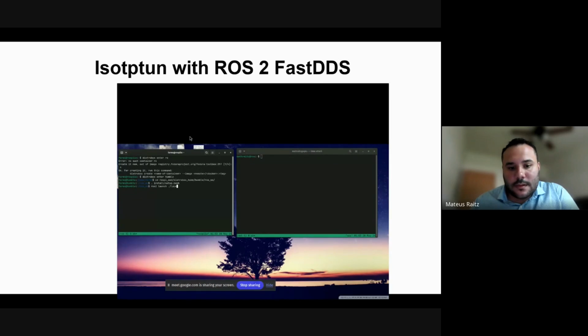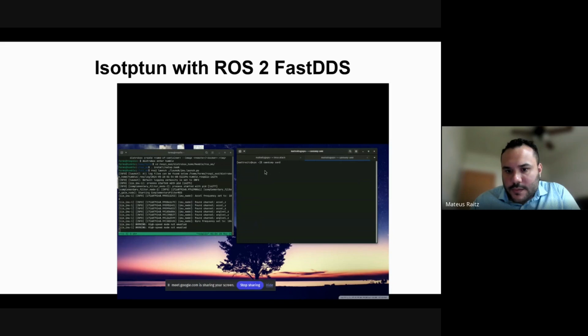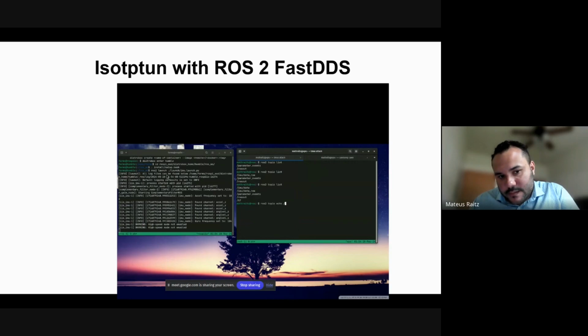So here I will launch a node, SSHing into my Raspberry Pi through the CAN Ethernet. Here I launch an IMU node on my Raspberry Pi, and here we'll do a CAN dump just to see all of the CAN messages on that CAN interface. Now the IMU data shows up in my ROS running here on my desktop. It's being published by my Raspberry Pi.